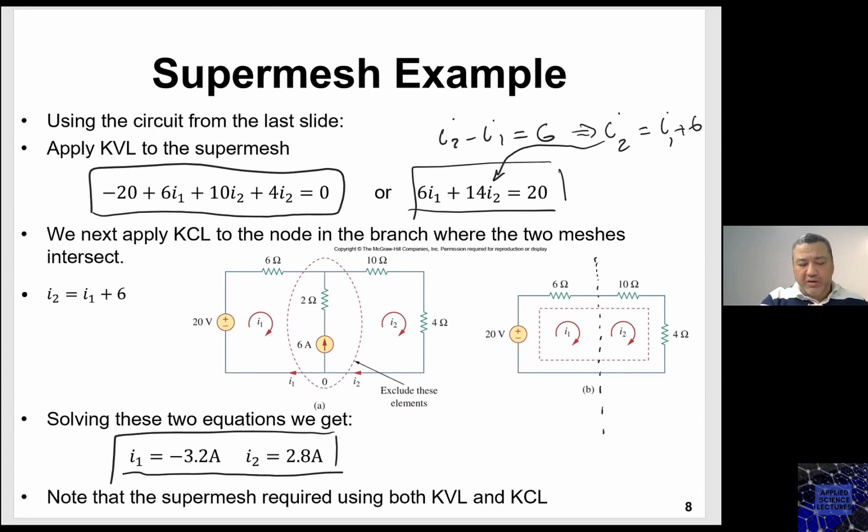Remember in nodal analysis, we had a super node, we were jumping between the sides of the super node, from one side to another side, where we have two variables that are bound, right? We finished the first part, and then we went to the second voltage node within the same super node. Here we're doing the same.